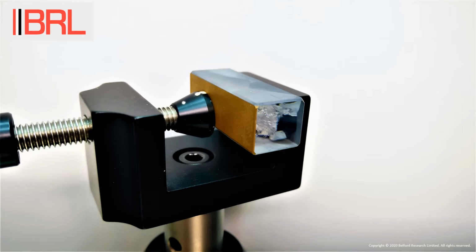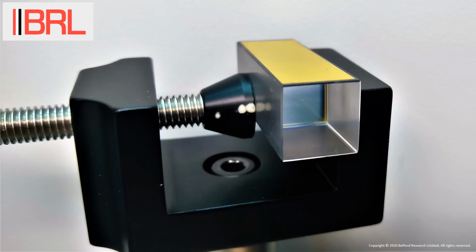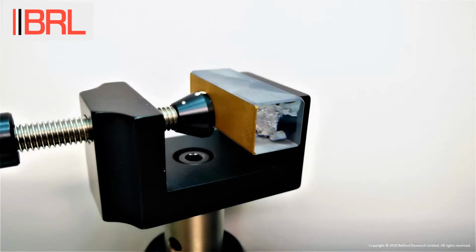This is an intracavity Q switch called lithium niobate. It is a coated electro-optic crystal. Lithium niobate can damage at the front face, or at the rear face, or even inside the crystal itself. Here it is before, and this is the damage event filmed from above. This is extensive damage, which is due to both the substrate damaging and the surface ablating.